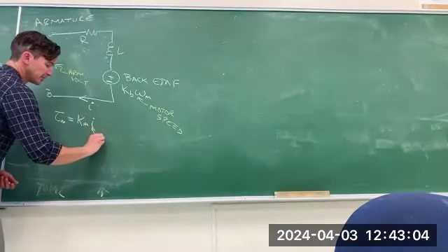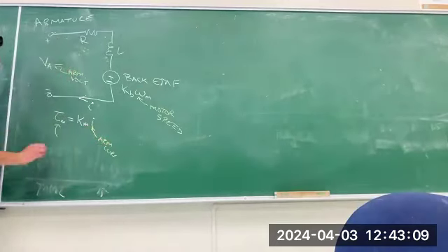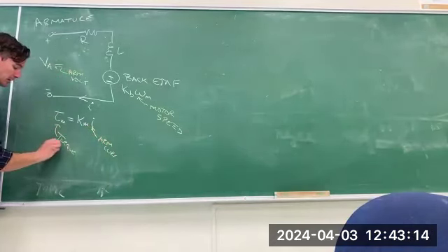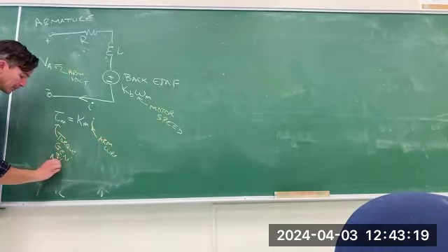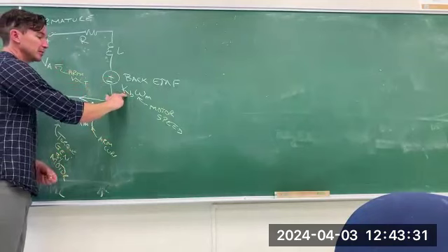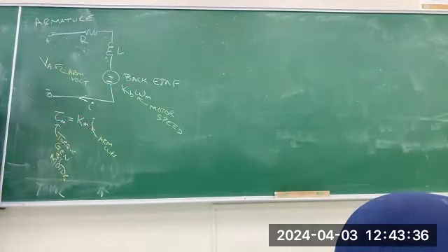So I is the armature current, and tau sub m is the torque generated by the motor. And these Ks are simply proportionality constants, saying that the voltage here is linearly proportional to the speed, saying the torque here is linearly proportional to the current. More current, more torque.